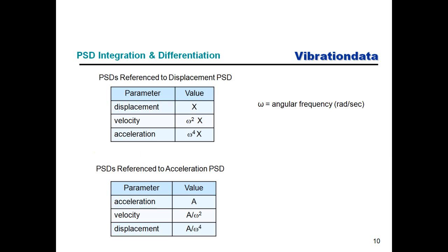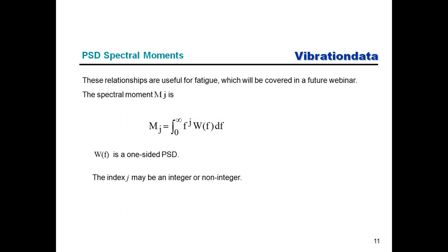And just also to remember, by way of analogy, anytime we are doing an integration, it's kind of like a low-pass filtering operation. Just in your mind's eye, think about, as we get to lower and lower frequencies, that velocity PSD is really going to jump up in terms of its amplitude at lower frequencies, and even more so for the displacement PSD.